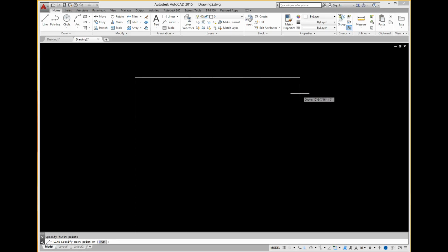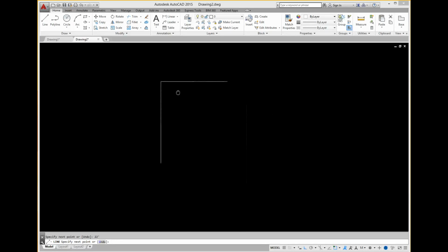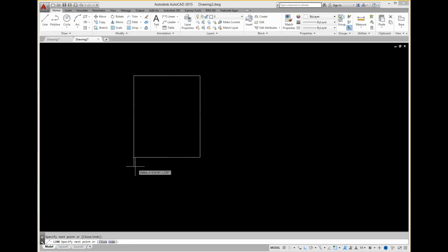Now let's type 22 foot. Enter. And once again, it's the apostrophe symbol that we use for feet in the architectural drawing system. So now we're going to pull down. You notice I didn't click on line again. You don't have to. You can just keep going. I'm going to type 27 foot, enter, and then come back and hover over this icon, endpoint, and click. And now I'm going to enter again. You can also escape to get out of there.